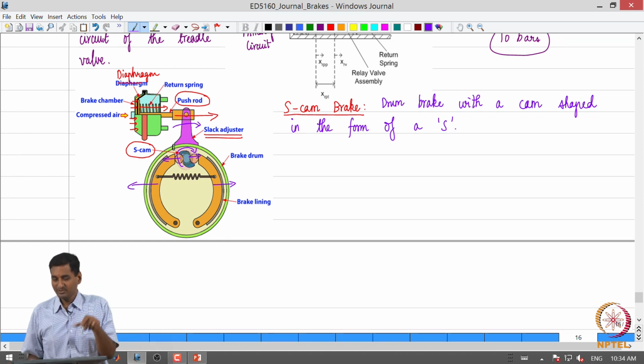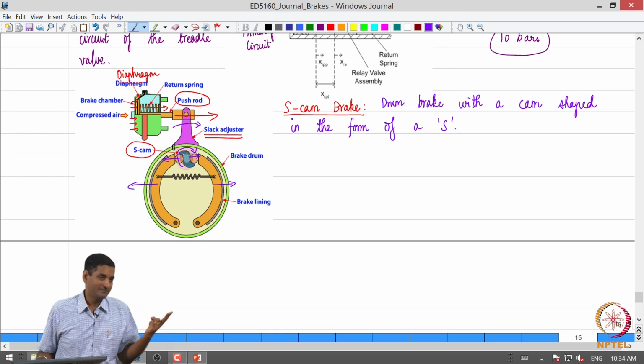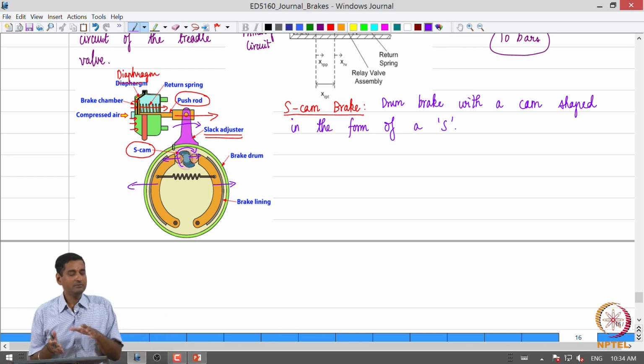Right, actuation force in these fluid based actuation systems will be pressure times area at steady state. So, if I want one order of magnitude more actuation force, I need higher actuation pressure or higher actuator area, or preferably both, right. Now, actuator area is constrained by the dimension of the drum brake. I can't put a big actuator in the space available. Actuating pressure in air brakes is one order of magnitude lower than that of hydraulic brakes.